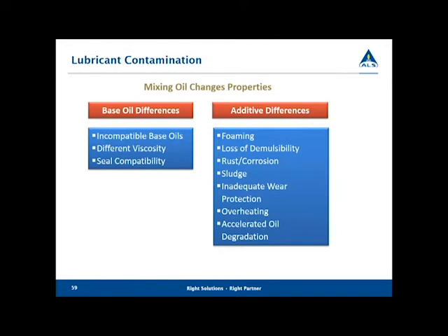Additive differences, well, if you mix oils or greases, you could bring about foaming, loss of demulsibility, rust and corrosion, sludge, inadequate wear protection, overheating, accelerated degradation. Why? Because these particular molecules are always competing to do something. And if you put different chemistries in there, if the research and development hasn't been carried out fully, you're going to have deleterious effects.